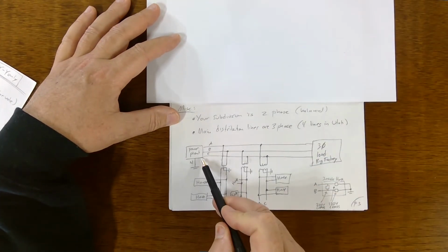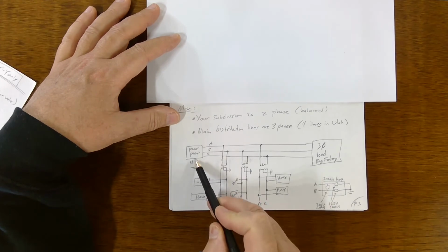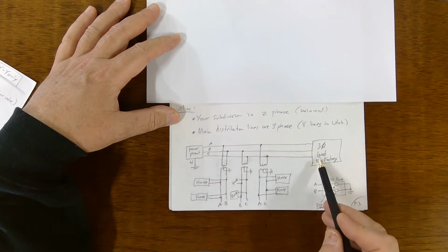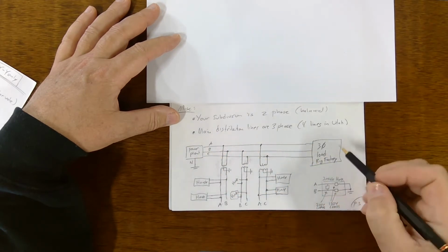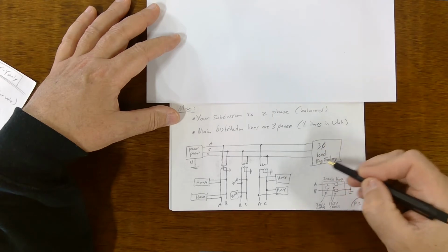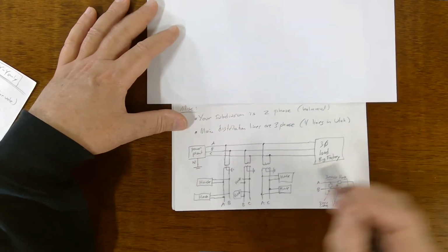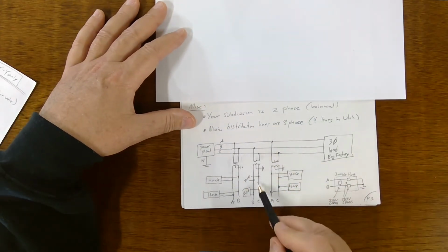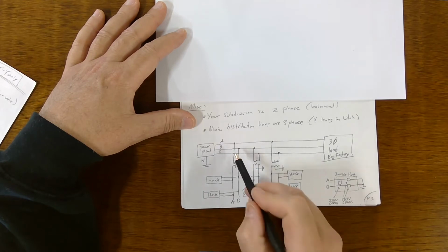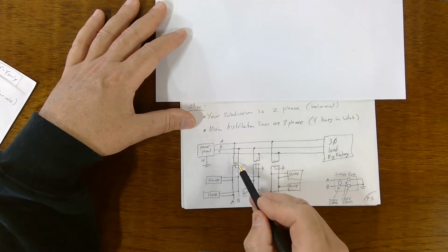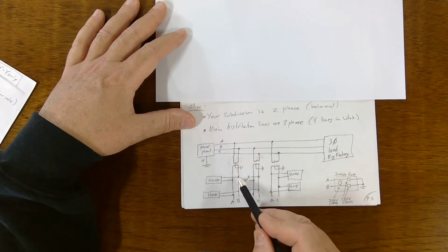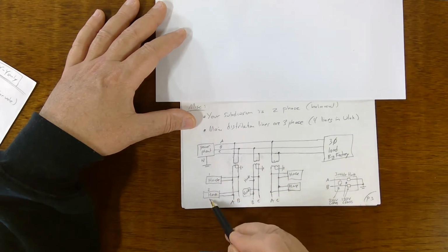So there's three phases coming out of the power plant. The neutral is grounded. Those three phases go out across the country. They could go, all three phases could go over to this big factory that has, say, one giant machine that uses all three phases. That could happen. Or you could balance the load like this. Subdivision A, subdivision 1, subdivision 2, subdivision 3. Subdivision 1 pulls off, say, A and B phase, and this goes to 100 houses. This is house 1. This is house 2, all the way down to 100.